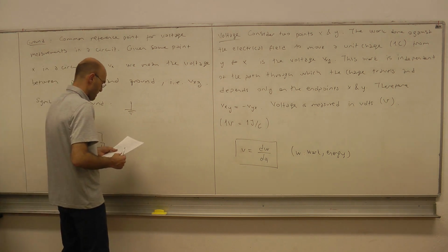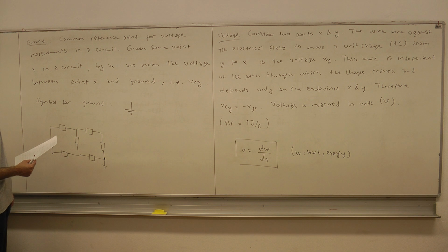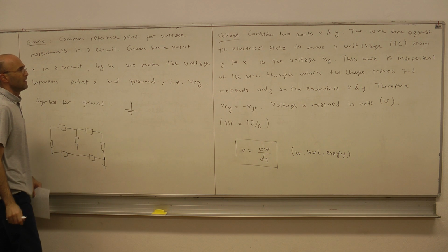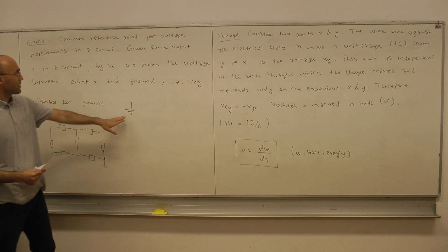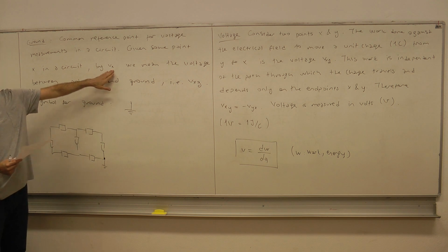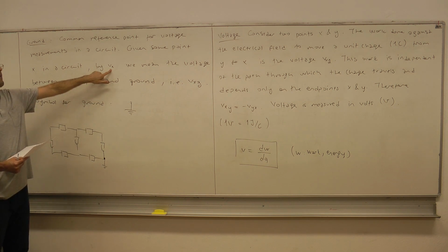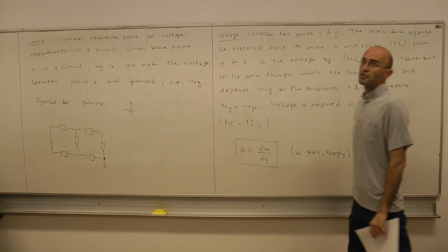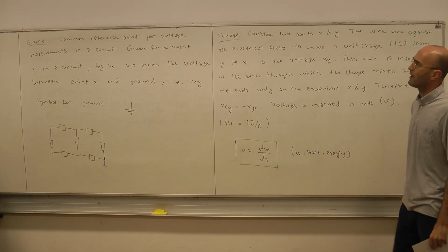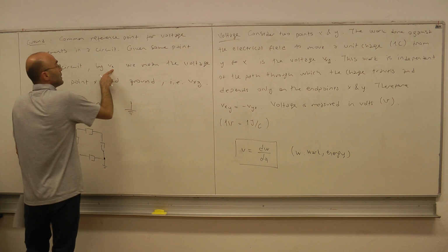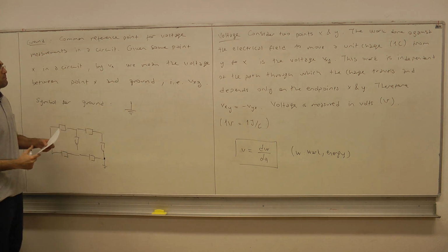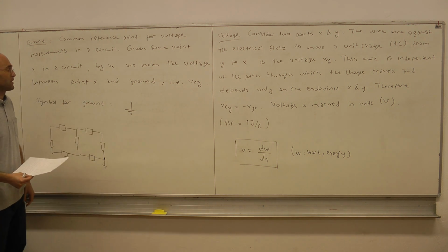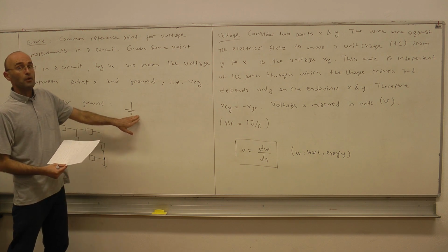Now we can talk about power. Well, before that, let's be clear about this V of x. Note that if the ground is not given, then this is ambiguous, because we're talking about the voltage of a point x, but the very definition of voltage requires two points. So this only makes sense if implicitly we have defined, or we have given, the ground node in our circuit.